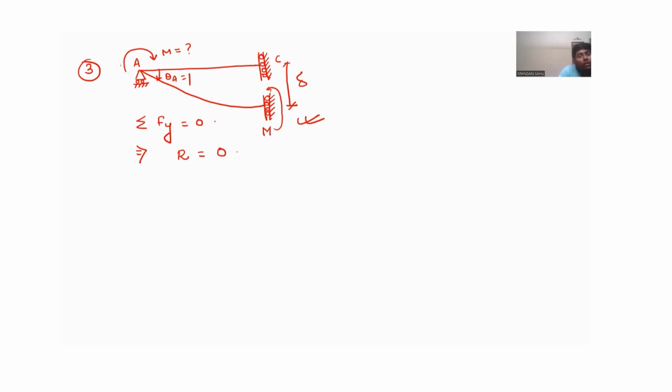Now, for this structure, if you draw the conjugate beam again, how will the conjugate beam look? Tell me. To draw the conjugate beam, you need to go to the joints, see the slopes and displacement of your real beam, and check if those are zero or non-zero.